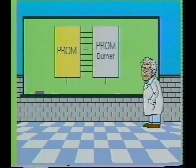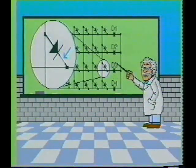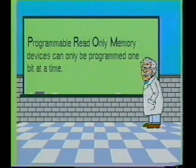To program the PROM, a special piece of equipment is used. It is called a PROM burner. The factory fresh PROM consists of a matrix of fusible links. An intact link produces a binary 1, whereas an open link produces a binary 0. PROMs are programmed one bit at a time.